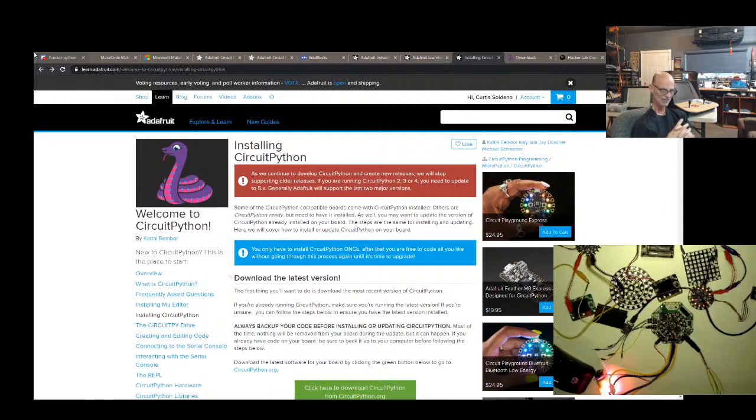Lately, I've been noticing they save out as a PNG file, as an image. It'll actually be a thumbnail of your project, and the thumbnail itself has the code embedded inside of it. So you drag and drop the image thumbnail onto the MakeCode interface, and it will unpack it, and then you'll have all of your commands there. It's strange, and I don't have my hands fully around it, so it's not something I would suggest trying to utilize unless you understand it better. So the UF2s can be saved directly to the device.